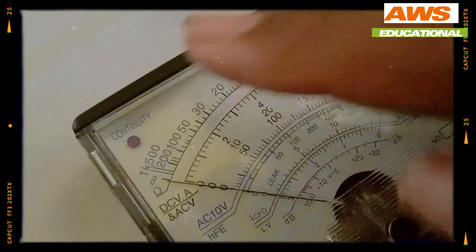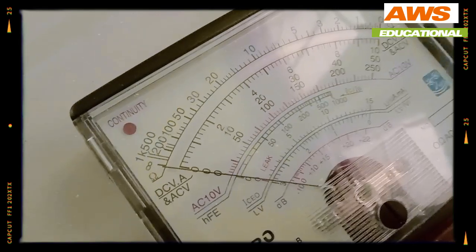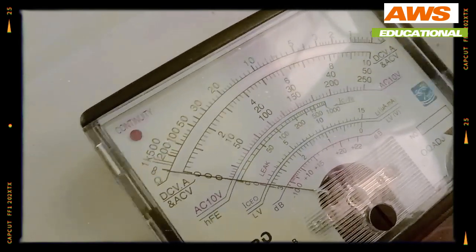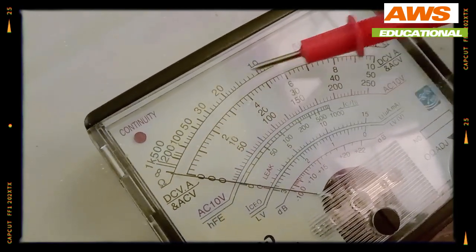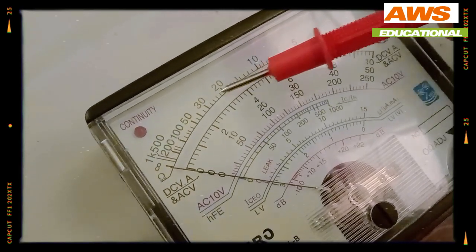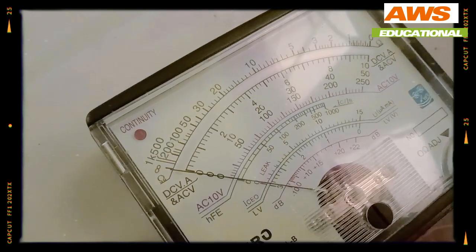Steps for the use of analog multimeter. 1. Insert the probes into the correct connections. 2. Set the switch to the correct measurement type and range for the measurement to be made. While selecting the range, ensure that the maximum range is above what is expected. The range of the multimeter is then optimized for the best reading.